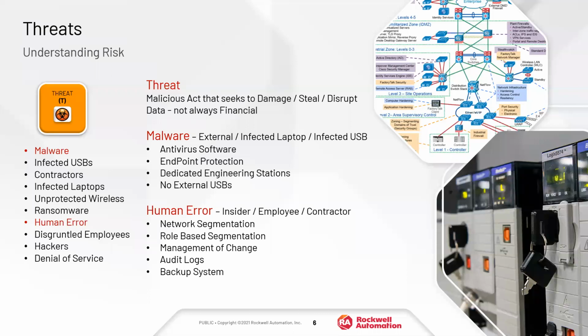We've all been there, done something by accident, connected into the wrong network controller. Specifically, if everything is networked and you're tying in directly to the panel in front of you, if you don't know the correct IP address and you're connecting in via Ethernet, there's nothing necessarily preventing you, if no countermeasures were done, from connecting into another controller, another VFD, by accident.